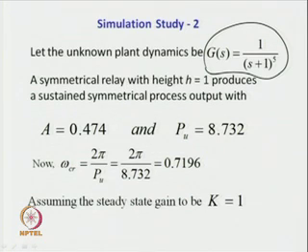So, the actual plant is something else, whereas we are going to estimate the plant dynamics by some first order transfer function model. What is that model? So, we are going to estimate this dynamics by some equivalent model GM(s) of the form K e to the power minus Ds upon Ts plus 1.